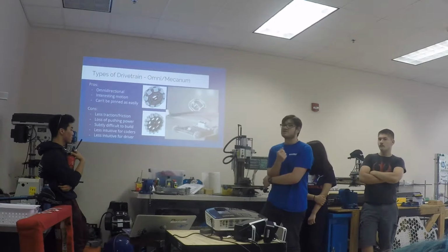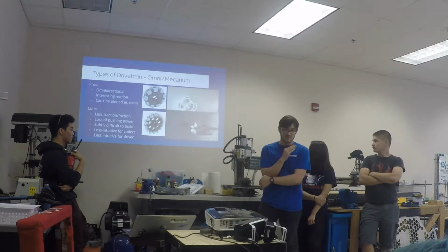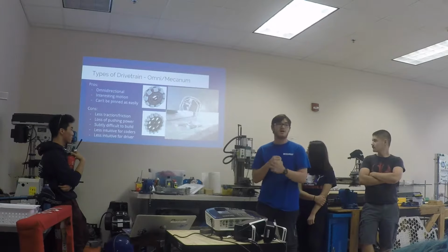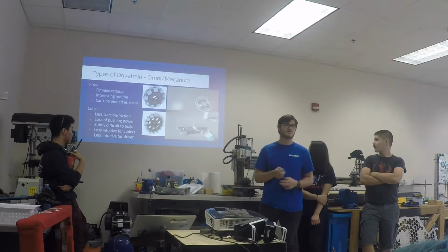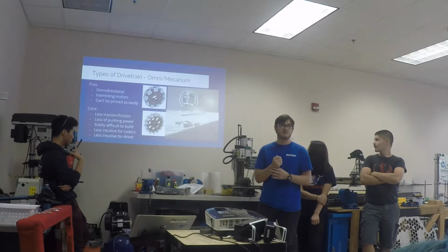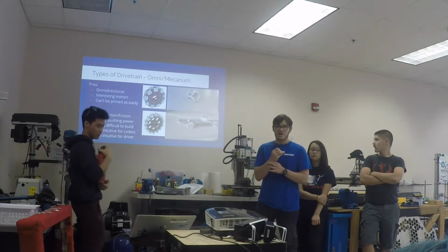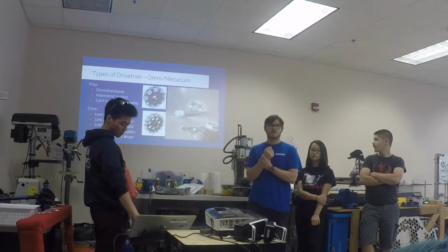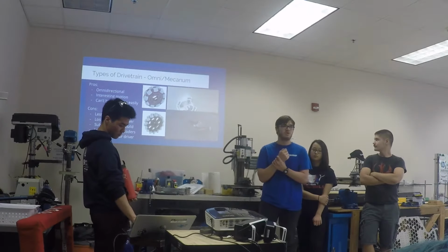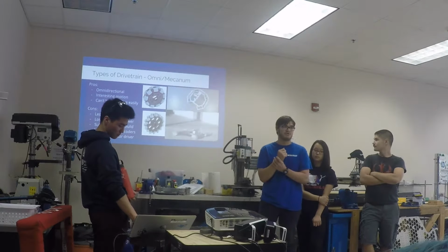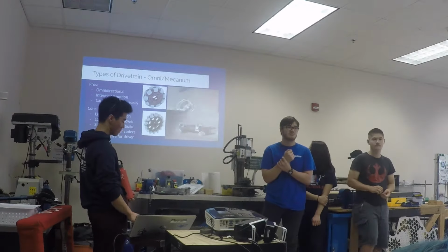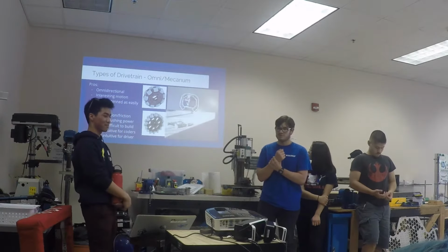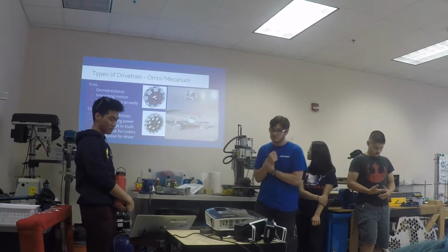Then we've got Omni/Mecanum wheels. Mecanum are kind of a joke, but they can be used to great effectiveness. Omni wheels are wheels that allow you to not only move forward, but also sideways. So that gives you complete omnidirectional movement. However, it generally sacrifices torque, and you don't have as much traction because the ability to roll in every direction means you can be knocked around in every direction. But if you need to cut corners really fast or optimize your ability to get somewhere, Omni wheels help with steering and directional mobility.